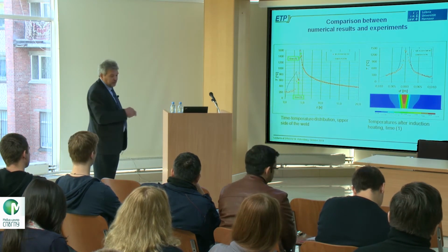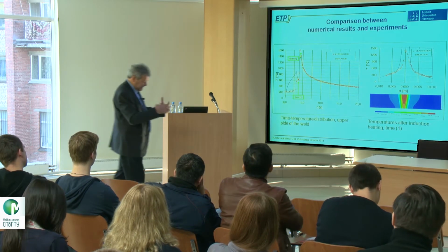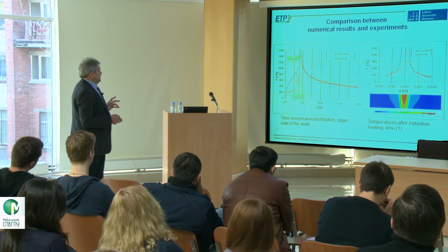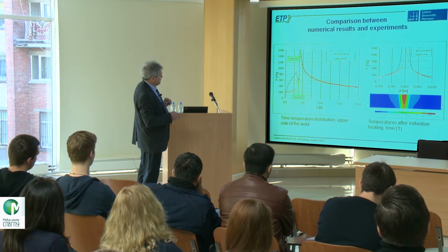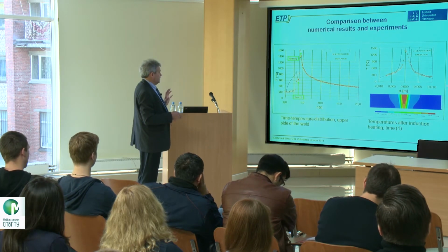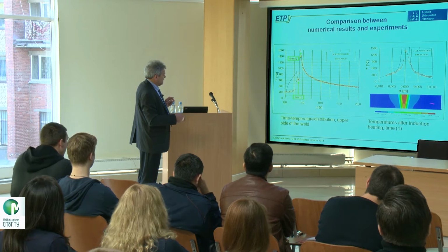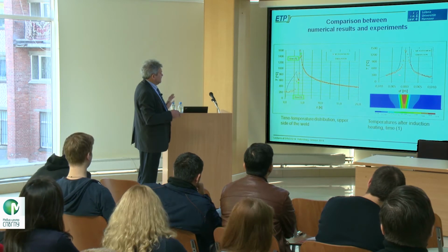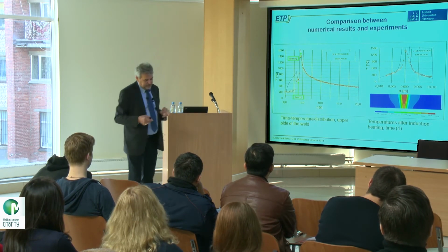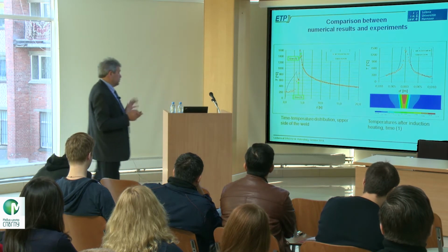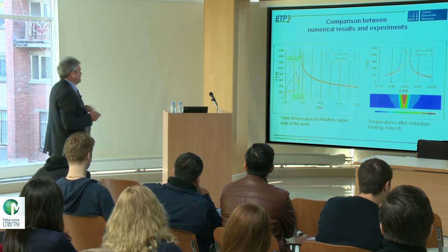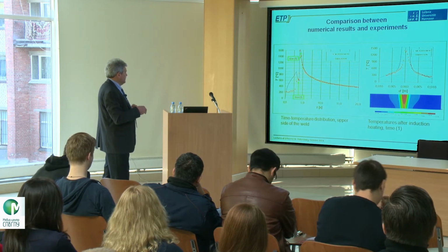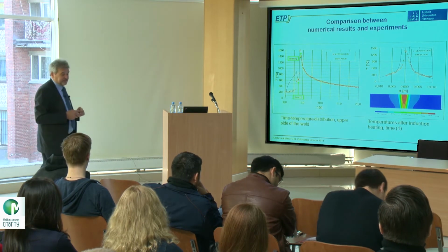So after laser welding, of course, you can try to bring heat in to reduce the cooling, to increase the cooling time. And here you see the diagram how the heat is induced over the width of the seam. So just in opposite direction. And of course, then you can control this width again by frequency, and of course also by heating time, and to control, let's say, the amount of heat you bring in here to increase the T85 time.